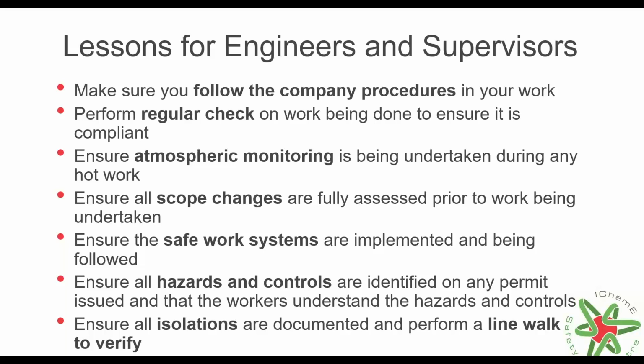Ensure that the safe work systems are implemented and being followed by everybody. Ensuring that all hazards and controls are identified on any permit that's issued and that the workers understand those hazards and controls. And again, making sure that isolations have been documented and performing a line walk as a supervisor for any work that's taking place.